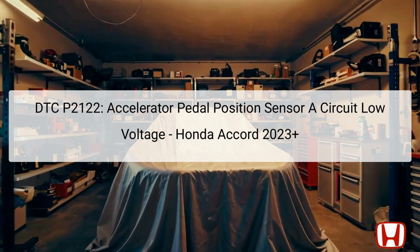It's important to address this issue swiftly to maintain vehicle operability and safety, as incorrect throttle readings can impact engine performance and vehicle acceleration. The DTC P2122 specifies that the APP sensor A's output voltage is less than expected, signifying a malfunction within the circuit.